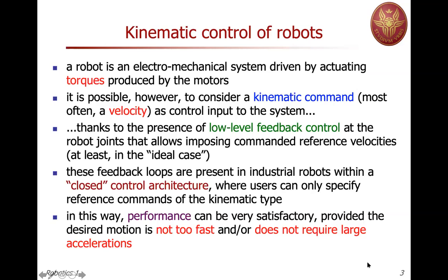this works fine, provided that the motion that you would like to execute is not too demanding, which means that it's not too fast, and this is why we also introduced the time scaling, or that it doesn't require too large an acceleration.